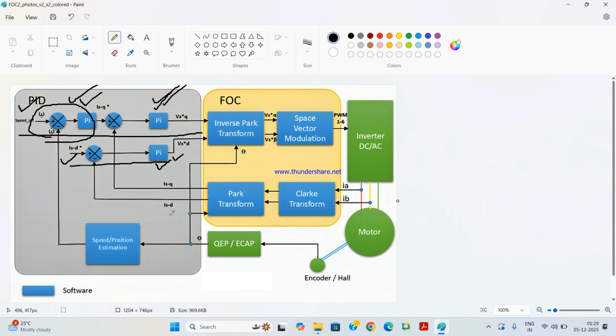So far, in my experience, it is very easy for low inertia machines and low voltage machines, but in medium voltage or high voltage machines, when the capacity is more than a megawatt, it's very tricky. The auto tuning will not work. Again, I am repeating, the auto tuning will not work. You will not get that much good response from the system.